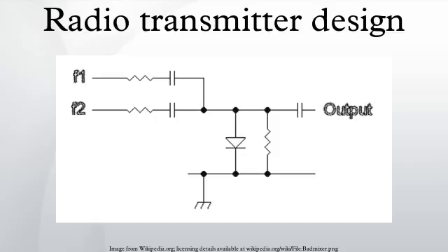If an intentional transmitter produces interference, then it should be run into a dummy load. This is a resistor in a screened box or can which will allow the transmitter to generate radio signals without sending them to the antenna. If the transmitter continues to cause interference during this test, then a path exists by which RF power is leaking out of the equipment, and this can be due to bad shielding. Such leakage is most likely to occur on homemade equipment or equipment that has been modified or had covers removed. RF leakage from microwave ovens, while rare, may occur due to defective door seals, and may be a health hazard.